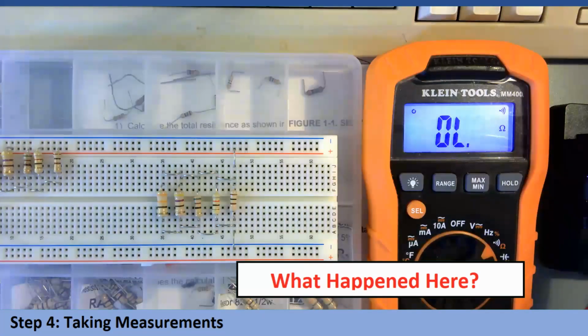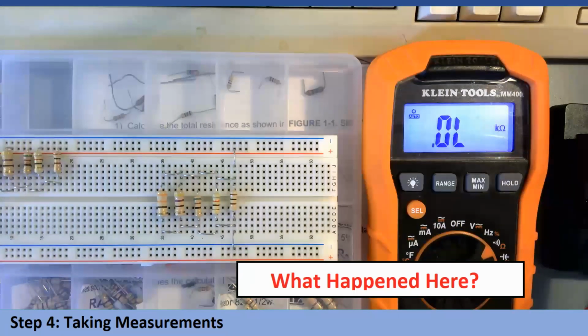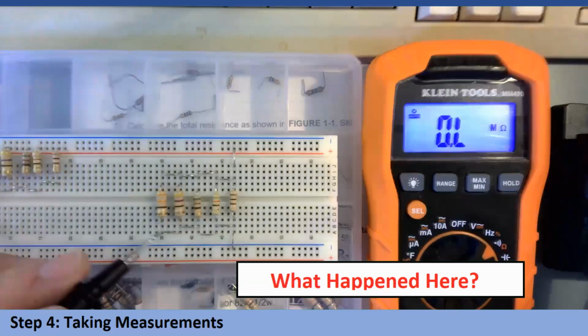We know that with this particular meter, at around about 50 ohms, after 50 ohms it will not release a signal. It will not give us an audible sound. Well, this one is under 50, this one's under 50, but the others, the 100 ohm, is above 50. So is the 82, so is the 51. Our resistance is much, much lower. Let's put it to resistance properly. And let's measure the total resistance from those 2 points again.